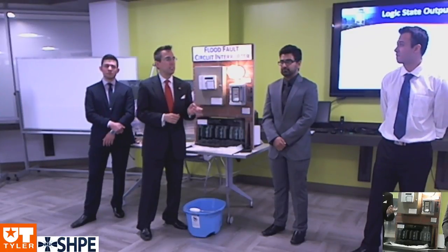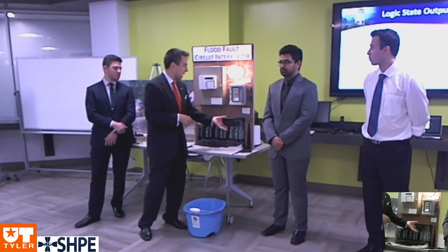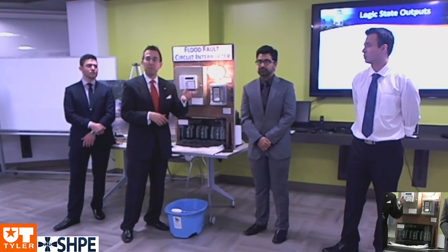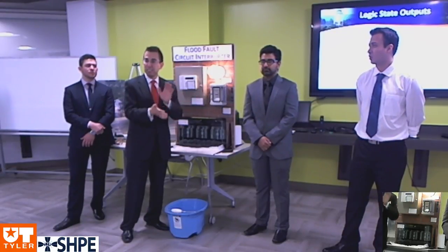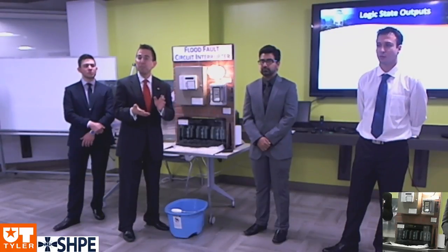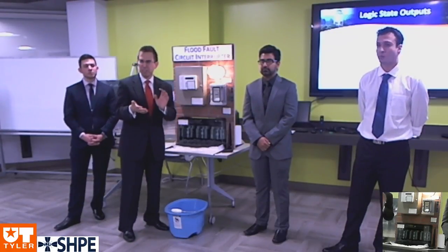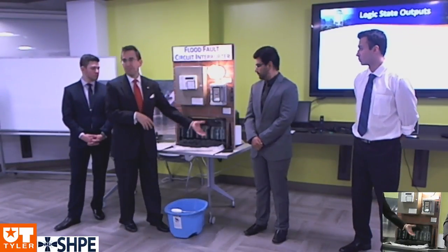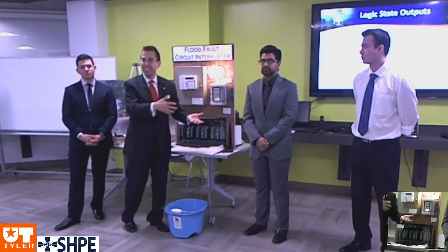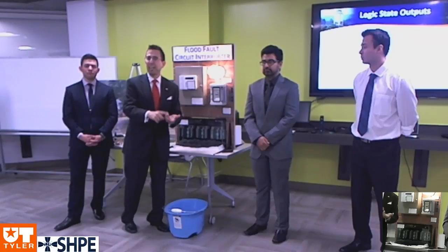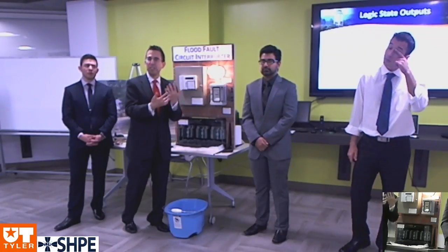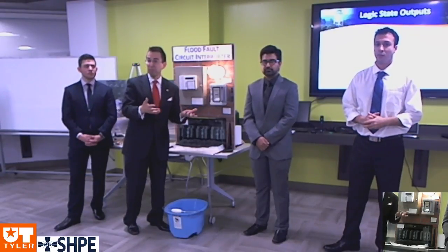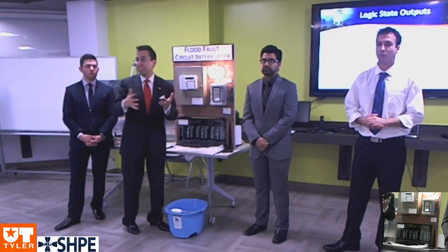That's a really good question because it goes to the applicability of the system across a lot of different designs. Now, the first circuit you heard from Cyrus was essentially that conductive sensor. That's typically used indoors because you don't mind a false alarm for water indoors, because why do you have water indoors? In other words, we designed our system with these complex float switches because we do expect humidity and water outdoors, just not enough to float a switch. So indoors, you might accept a simpler design that might be more reactive, because the intent is that you should less commonly see water.